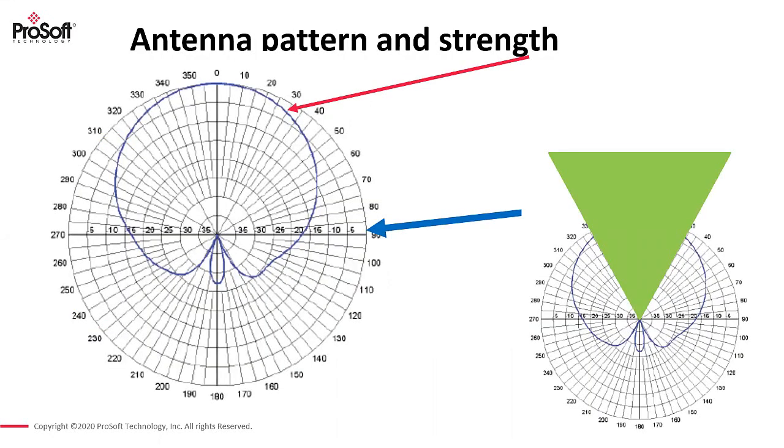On the screen here, we should see an antenna pattern. All antennas have different patterns. They'll send out a pattern that's horizontal as well as one that is vertical. This one here is for a panel antenna. The blue arrow shows us different circles: 0, -5, -10, -15, etc. These represent signal loss. And the red arrow shows us the angle of the beam, where I would consider full strength.